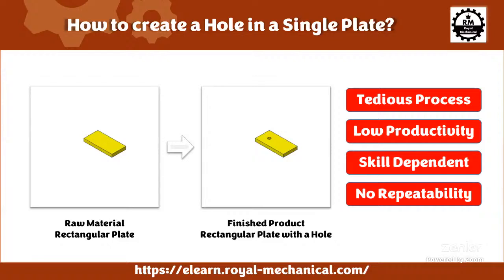For example, we need to ensure that the position of the hole is at a distance of 25 mm from the edges of the component. The operator might drill with some variation. For example, some components might come 25 plus 1 mm, some components might come 25 minus 1 mm. Sometimes it could be more. So basically there is no repeatability in the components.